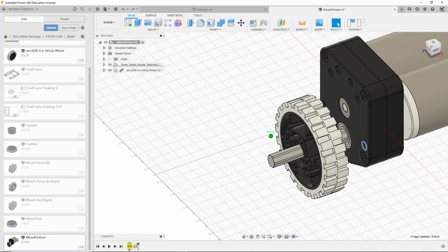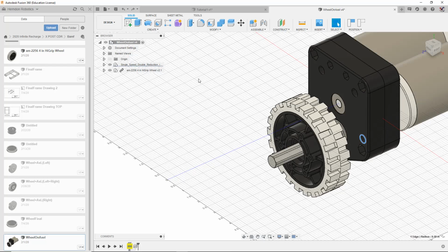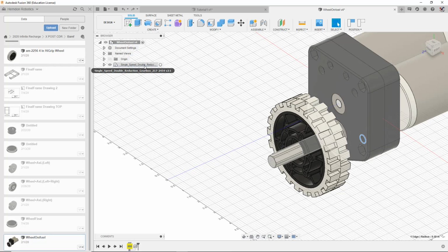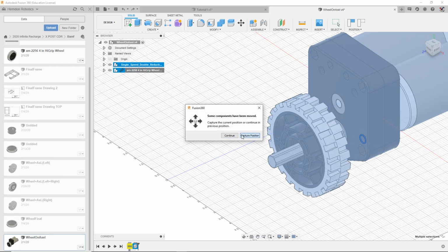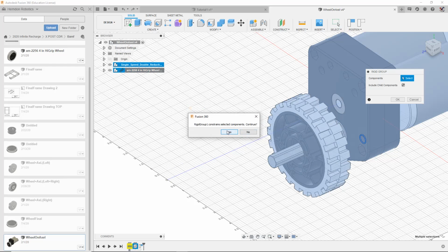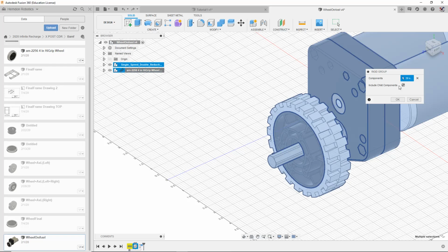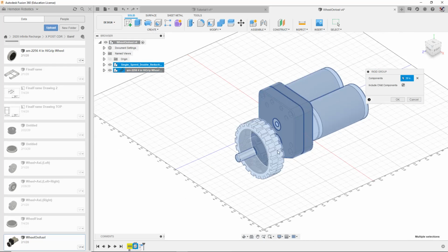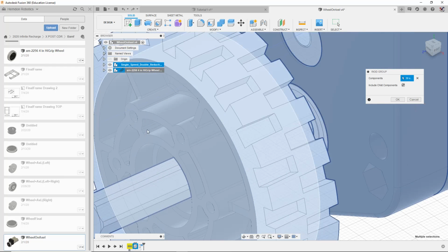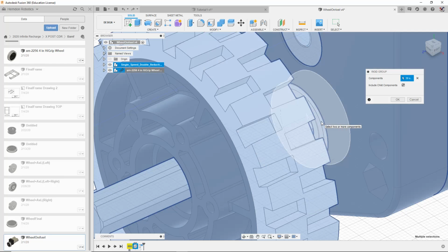What you do is you load all the files in the file. Normally, in this case, you just have bodies. You'd select them, and then you can just hit rigid group right here and hit capture position and hit yes. Including child components basically means all the components. So the wheel outside's a component. This could be inside as a component. The axle's a component. However many components there are ends up being how many the company made.